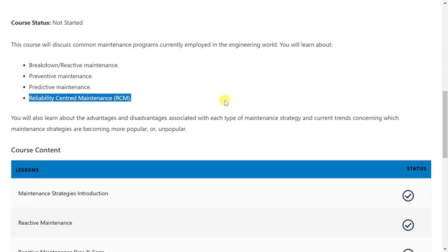So in summary, if we've got a motor that is 100% critical to the entire plant, such as a cooling motor or a motor associated with a cooling pump for a nuclear power station, if there was only one, which isn't going to be likely, but if there was, it would be very well maintained because it is absolutely critical to the entire process. The last thing we want is a nuclear meltdown just because the cooling water pump bearing failed or seized. So that's what reliability-centered maintenance is.